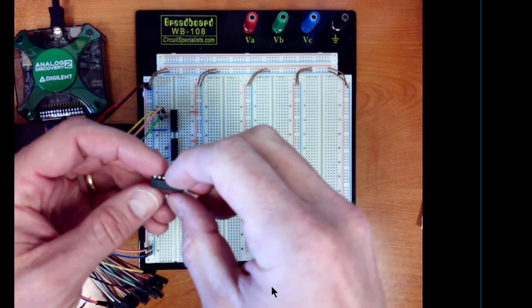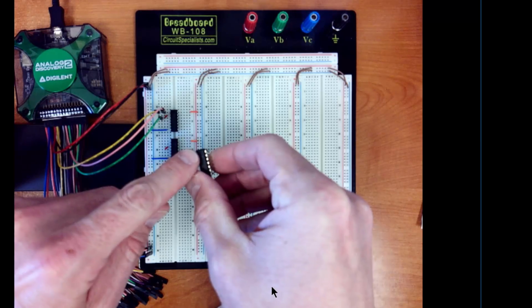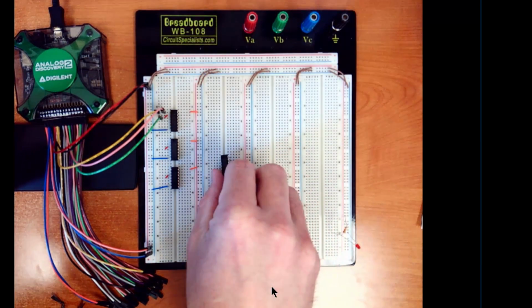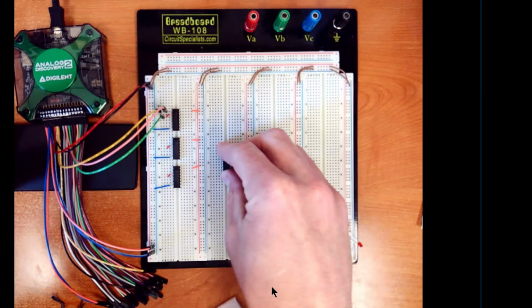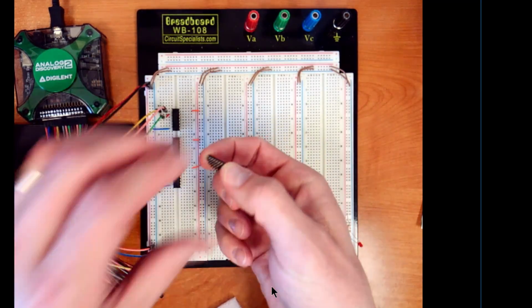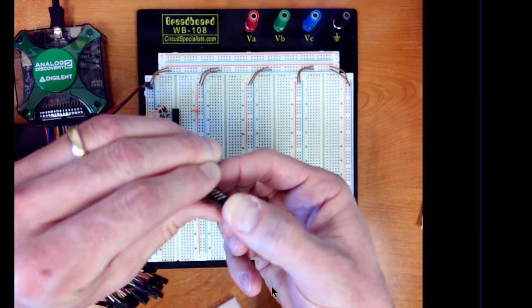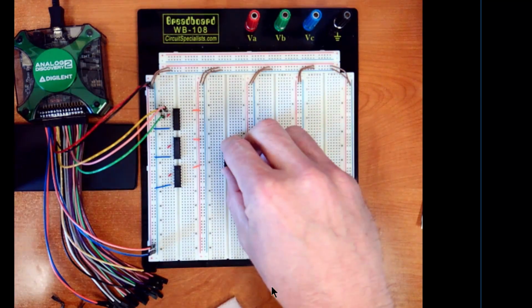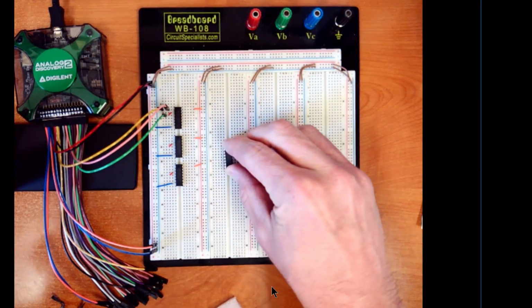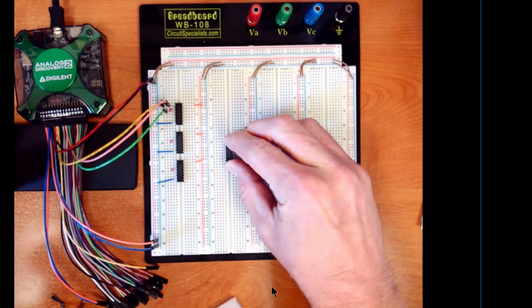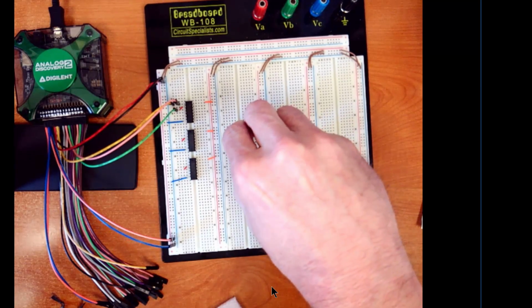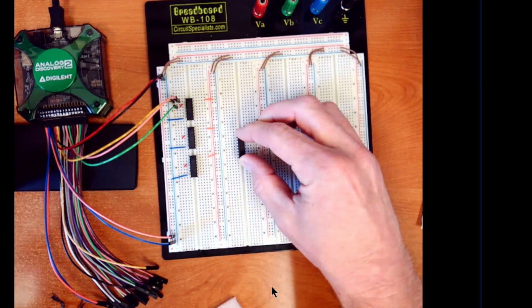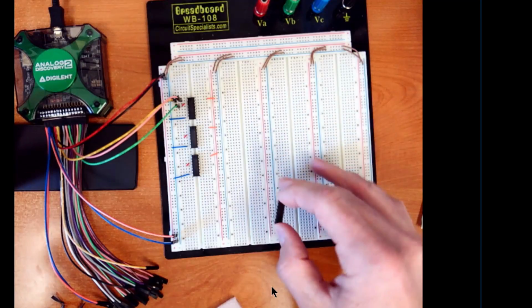And then you can always tell pin 1 by the little divot inside of there. These breadboards are actually designed to accept these parts straddling this center line. Okay, so I didn't get my pins in enough. Okay, and they're made to go just like that. So what I recommend you do is put your inverter, AND gate, and OR gate in just like this, boom, boom, boom.